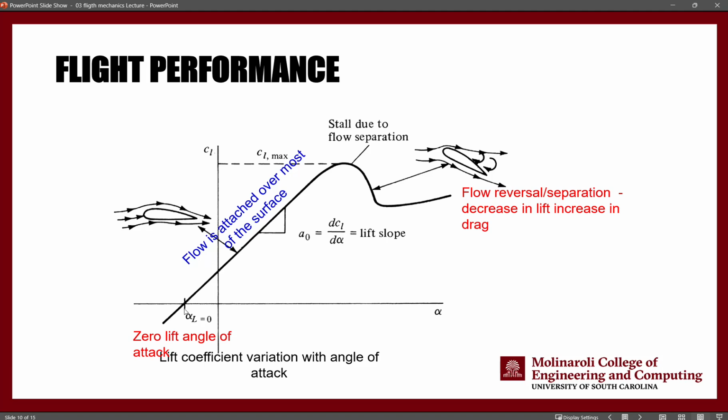Okay, so we start with negative values. There is a point at which lift coefficient will become 0. The angle of attack, which is the angle between your chord length, your airfoil, your wing, and the direction of the movement of the air, the wind direction, at that 0 lift is called 0 lift angle of attack. So when you are graphing this graph for your own lab, you essentially have to find this value for your specific aircraft, 0 lift angle of attack.